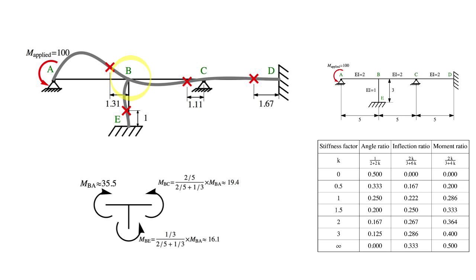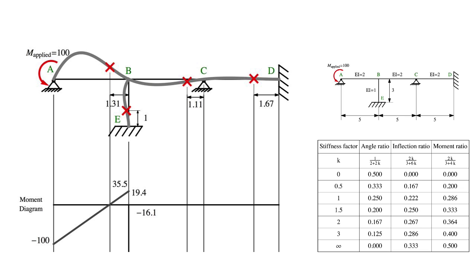To improve this, we could have used a typical reduction factor of 0.9 to get much lower errors, but the effort is not worth it. In practice, final results will be obtained using software, and these approximate methods are mostly used in preliminary design, in getting more insight and in having an expectation for the values of the computer output in case we make some input or interpretation errors. So now we have the bending moments at the joint of B.